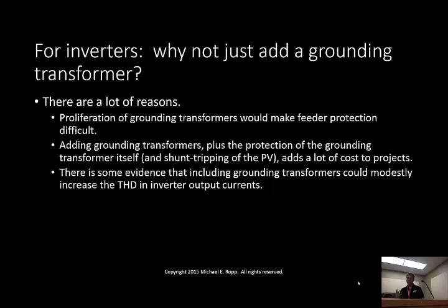One of the big things from the CUSP perspective, or from protection's perspective, is that, as you know, every grounding transformer that we put on the distribution circuit will make a contribution to the fault current for any asymmetrical fault. So envision a situation where you've got 4 or 5 photovoltaic plants on a feeder, put a grounding transformer on every single one of them. It's going to completely mess up our protection coordination. So that's not desirable either. What we want is a grounding transformer design procedure that offsets that problem by trying to take only the part of the fault current that is attributable to that PV plant. And I'll show you a procedure that does that in just a minute here.